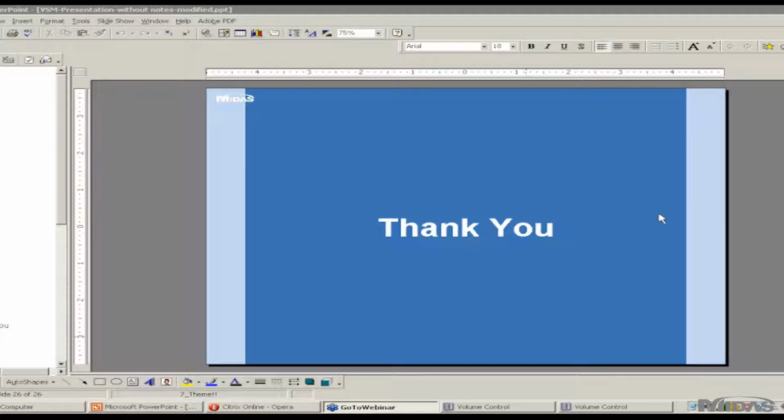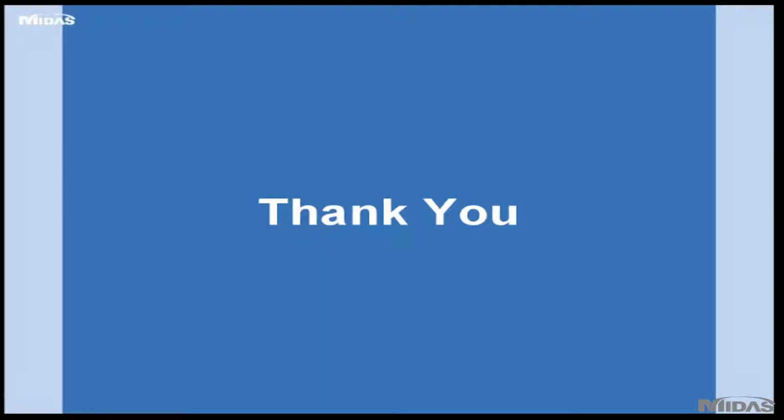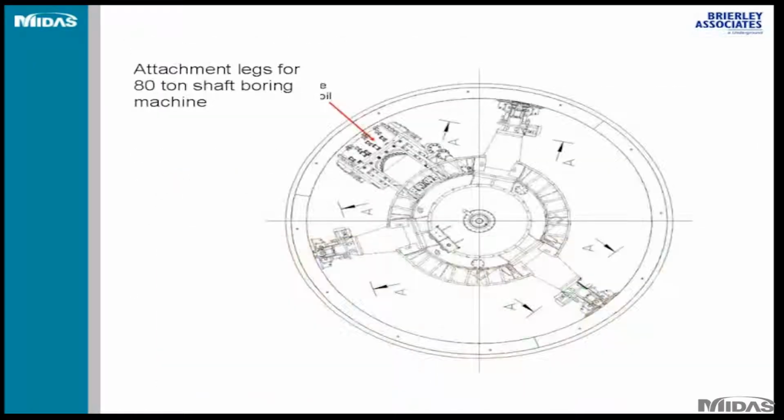I will go back to one of the drawings very quickly. This is the outer diameter here, as you can see. Using this telescoping arm, you can over-excavate. In fact, we ended up with 1 foot of overcutting, so you have an extra 1 foot outside the outer diameter using this telescoping arm of the grinding head.